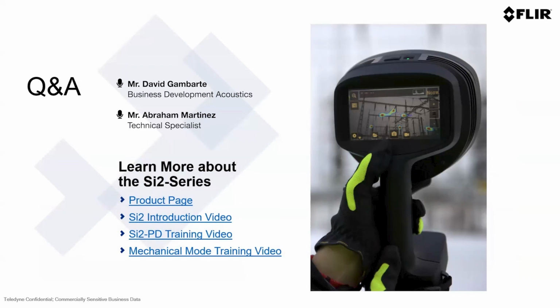And as well, if you are using the acoustic viewer, which is the online tool, I would recommend going to settings and setting up the CO2 cost. The CO2 cost needs to be set in order for the report to display the CO2 savings and emissions.